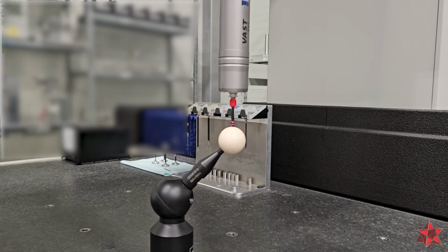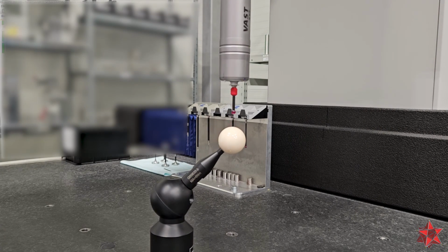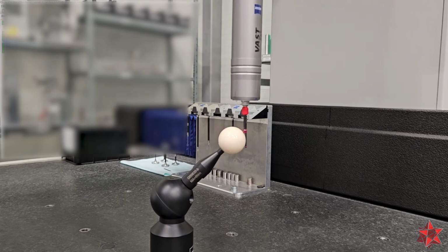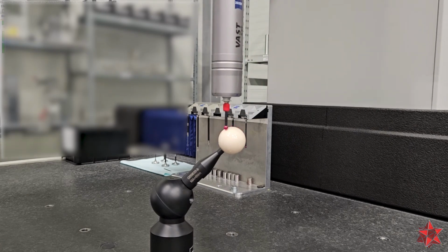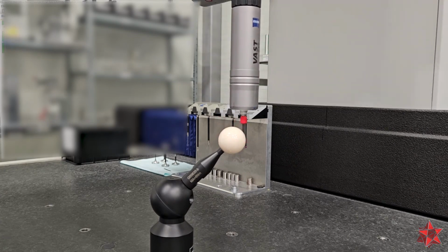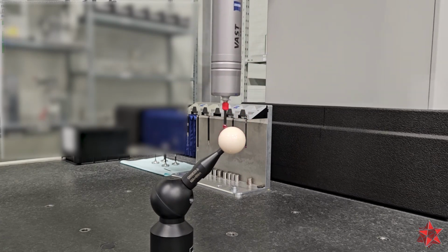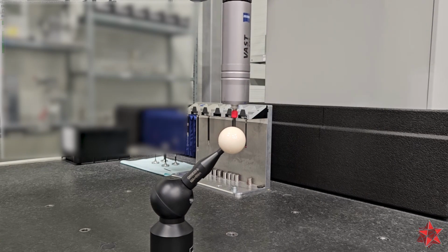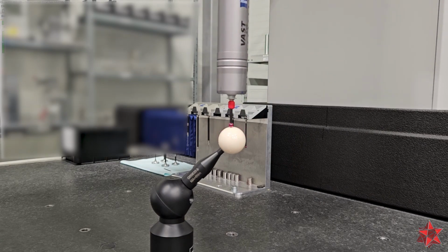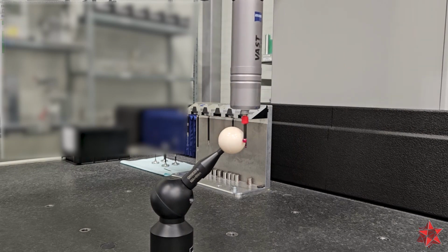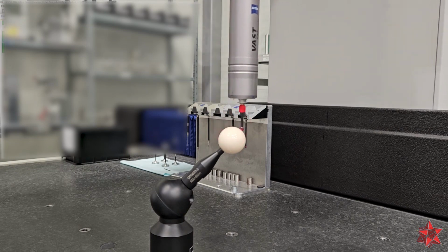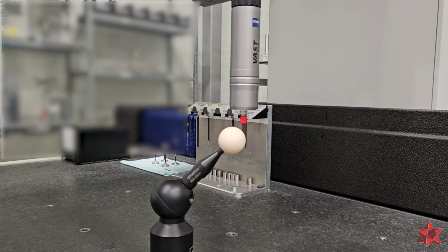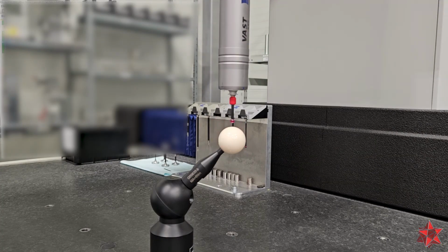Then wait for the CMM to determine the location of the reference sphere on the measuring table with the help of the master probe. This step is very important and cannot be skipped. Also, keep in mind that this step is necessary for manual probing and for automatic probing as well. So whenever you want to calibrate your stylus system or your styluses, you just have to do this step first. Just locate the reference sphere position on the measuring table with the master probe. Then you can go forward with your calibration.